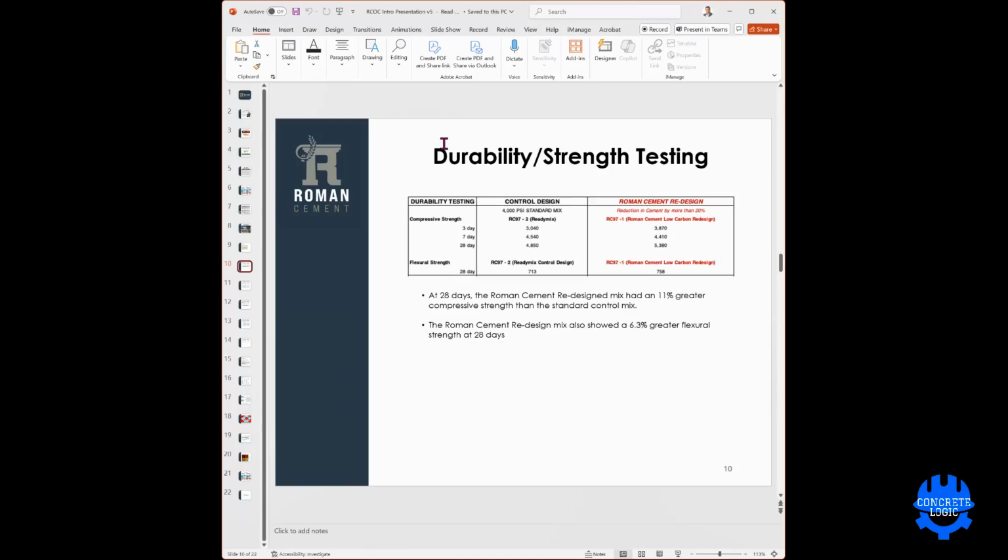Well, there's also some practical things, Seth. Depending on the strength and the mix design, you're not always going to want to have the same ratio of type 1L cement with this blended pozzolan or blended SCM, if you will. Different mixes right now have different amounts of fly ash or natural pozzolan, different ratios of cement and pozzolan. And we're going to want the batch plants to have maximum flexibility to adjust the amounts of these materials. Now, you get maximum adjustment if you put all three components in a different silo.